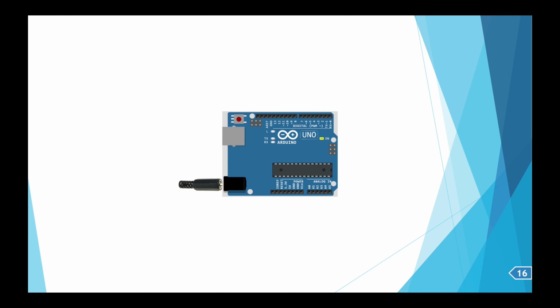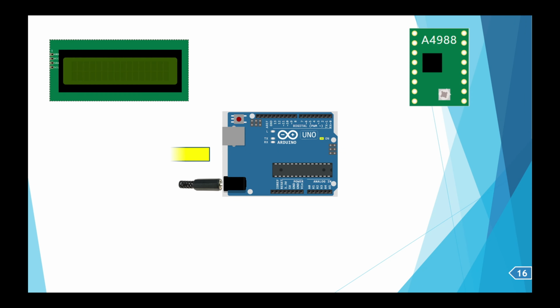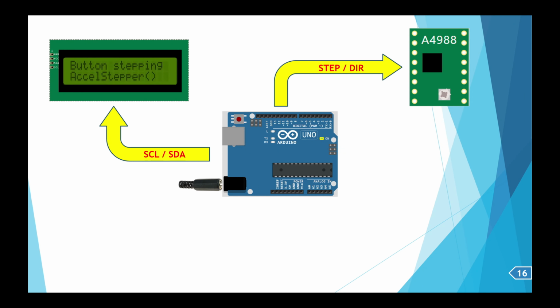As soon as the Arduino board turns on, it will supply some signals to both the display as well as the driver. And as soon as getting the supply, the display will be turned on and it will be available in the running mode. You can see that the default speed and position has been shown on the display. By default speed is 50 and the position is 0.